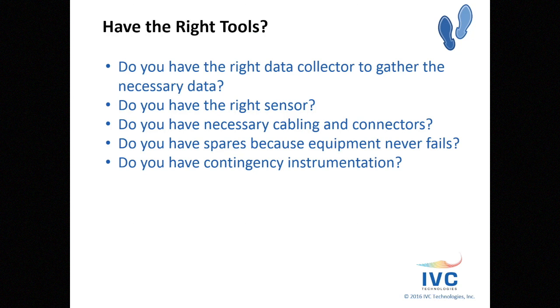Next step, do I have the right tools? Do you have the right data collector to gather the necessary information? We briefly touched on it earlier. If I'm going to make overall measurements, that's a simple thing. If I need to take spectrum or time data, that's another thing. It might require a different type of analyzer. If I need to acquire multi-channel data and stream it in, that may require a different analyzer, more complex setup again.